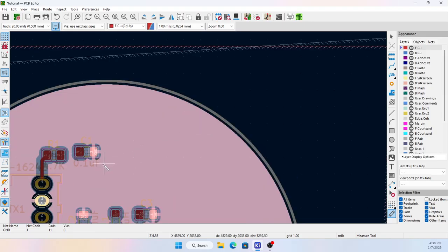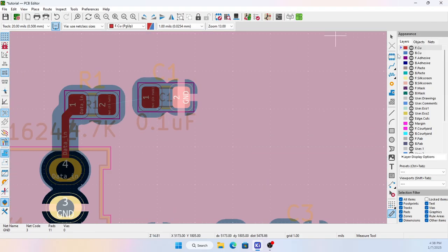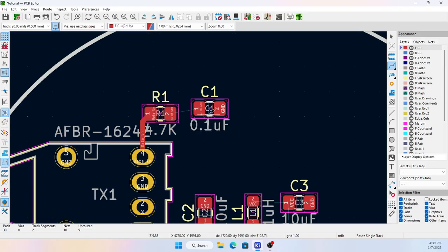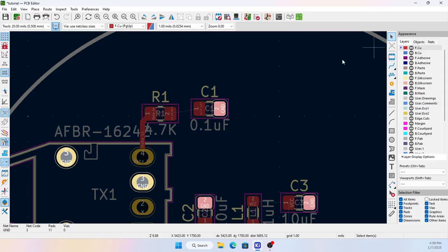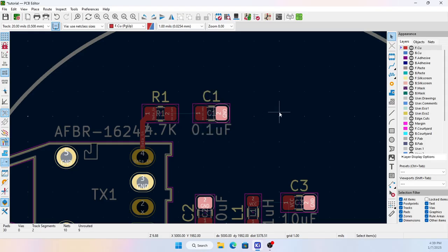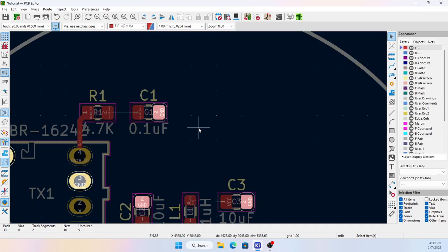All right. So let's go back to, so this bothers me right now. So I'm gonna click here, take that out. So now select this component, move, and put it straight up there. The ones that say ground, we're gonna put a via. So that's the default via.